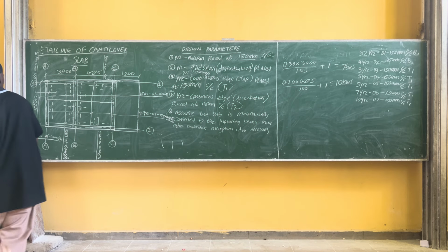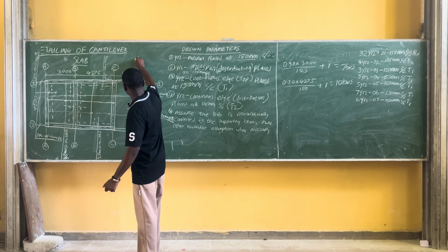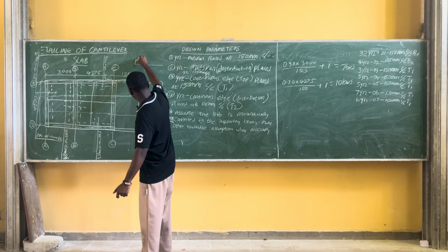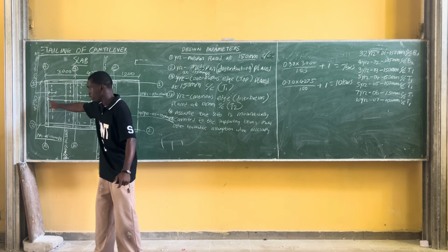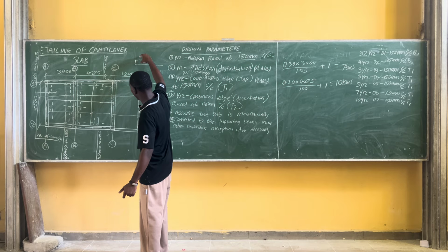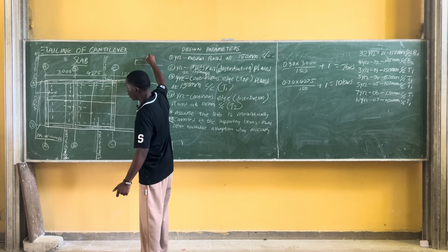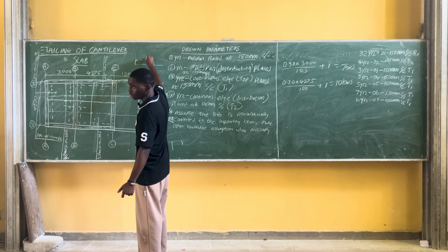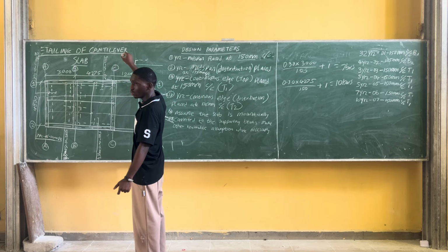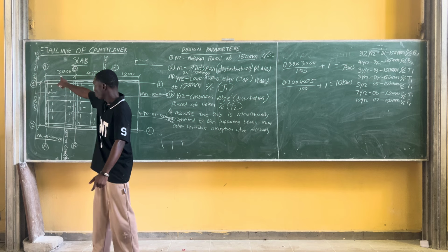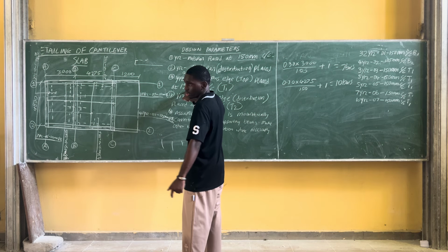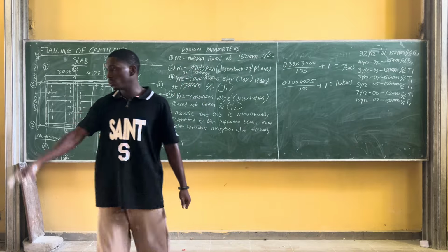0.15 is this hook. Remember that this is how it will be. This is how the slab is. This is the hook. So the 0.15 is this reinforcement bar that's spanning from here to here. That's 0.15. It's a constant given in the BS code. So 0.15 times our span, which was 3,000, divided by the spacing, 150, plus 1. That's how to get the reinforcement.